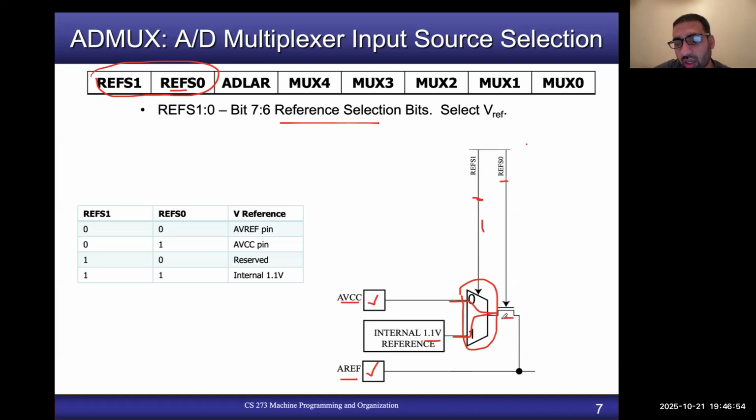This is nothing but a transistor which acts as a switch. So when you provide 1 as input at this one, this switch is connected. So basically the two sides of the switch are connected together. But if you provide 0 as input, then this switch is open. Which basically means the two sides of the switch are not connected, right?